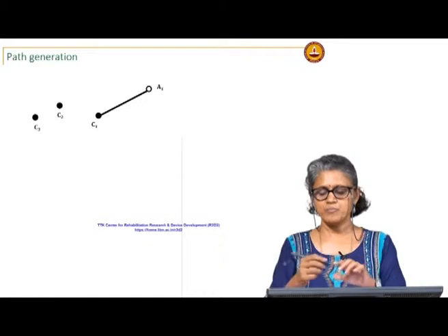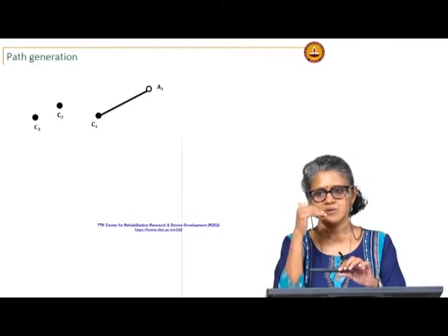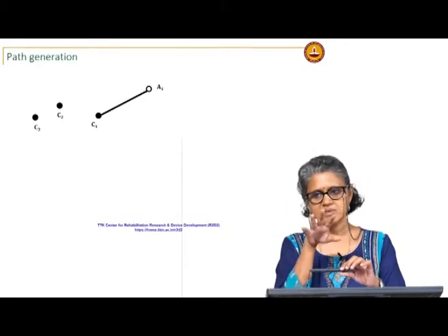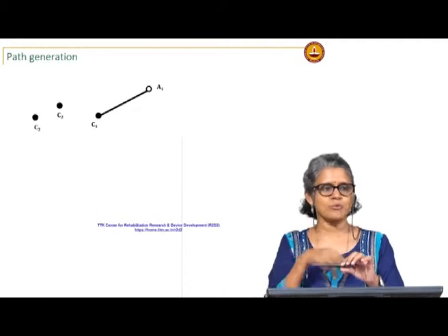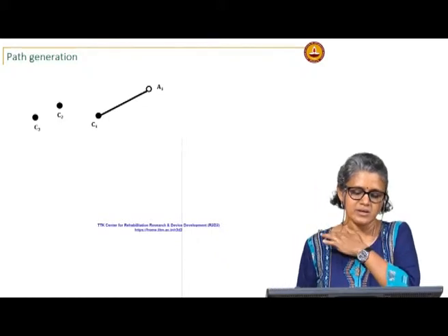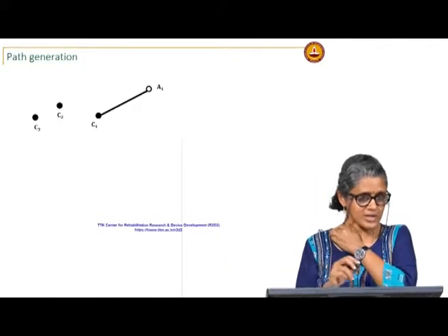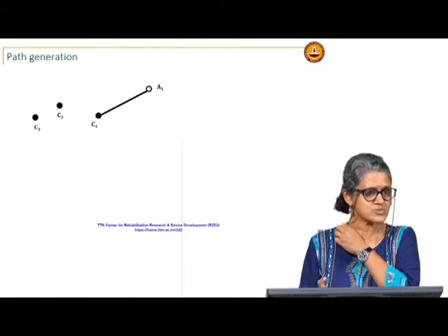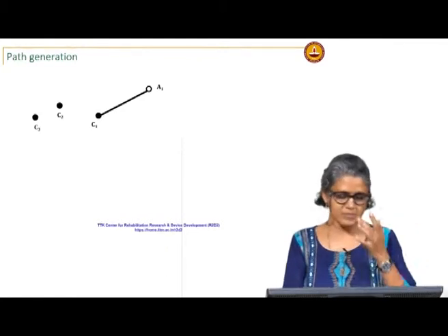With motion generation, 3 points is the limit, because with the constraint on both the moving pivots, you could no longer find a circle that passes through more than 3 points.